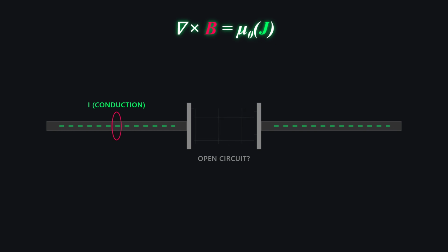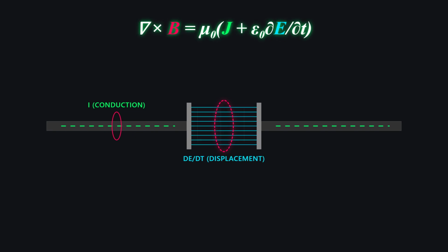a printed circuit board. However, Ampere's original formulation was incomplete when dealing with time-varying fields, failing to conserve charge in non-steady-state situations such as the charging cycle of a capacitor. Maxwell introduced the concept of displacement current to resolve the critical inconsistency in Ampere's law under non-steady-state conditions.